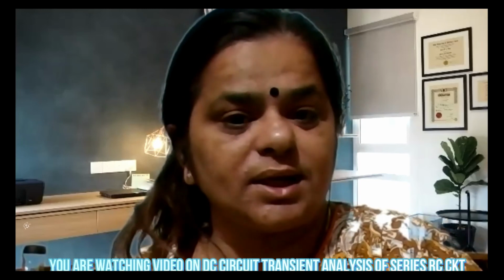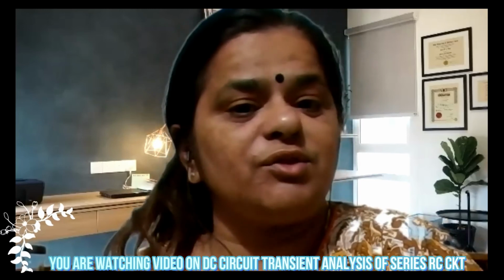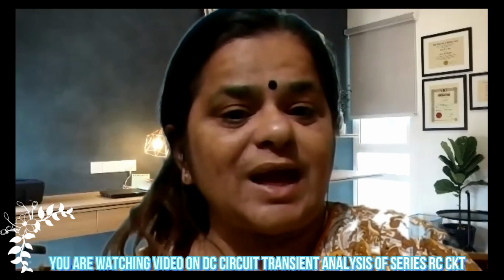Now my dear friends, whatever information I have shared in this video related to DC circuit transient analysis for a series RC circuit, now it will be clear to you. I hope you now understood the difference between steady state and transient analysis. As you have seen in the derivation, the current is exponentially decaying in a series RC circuit, and the voltage is exponentially increasing.